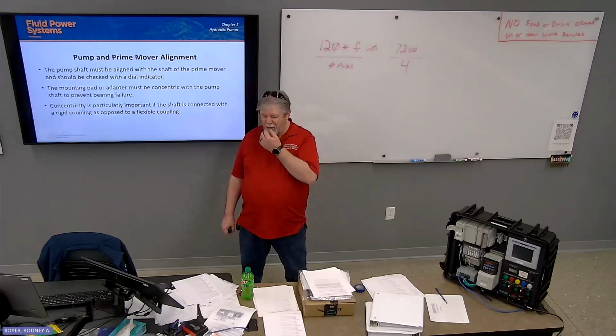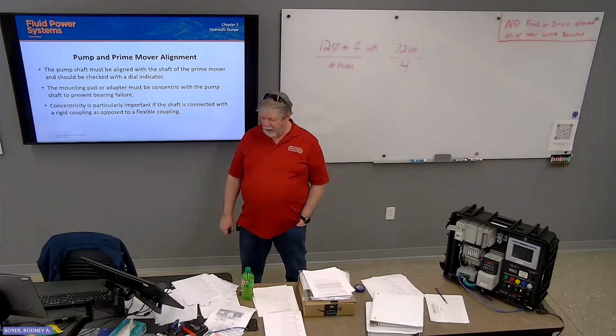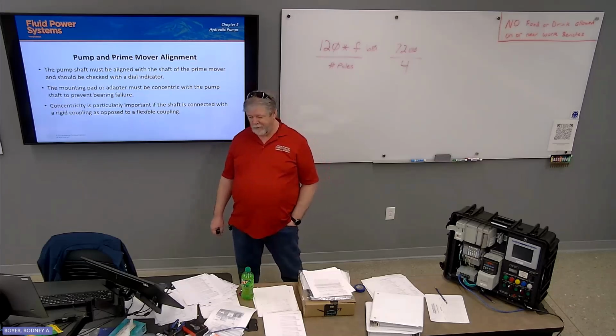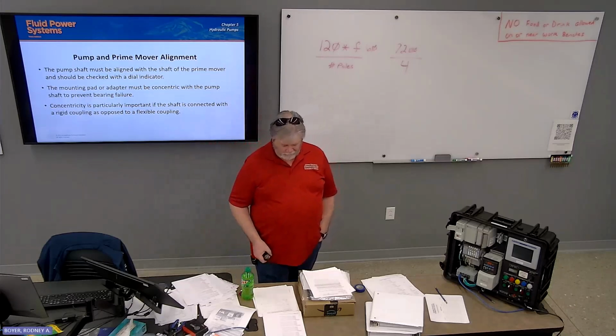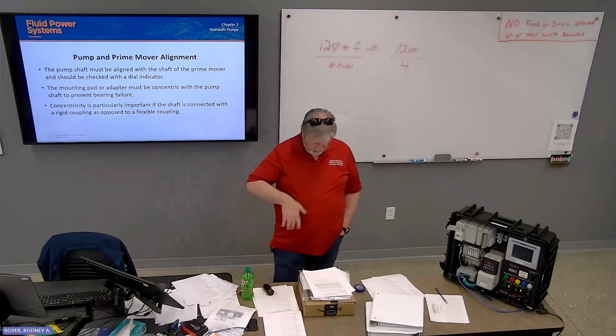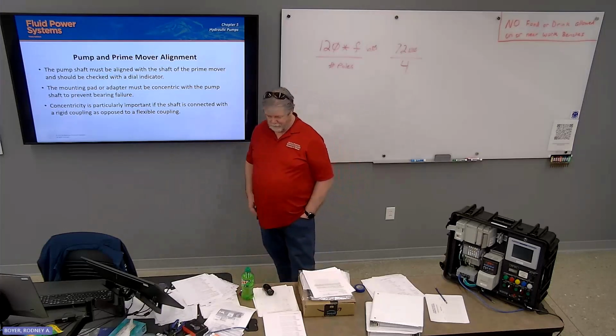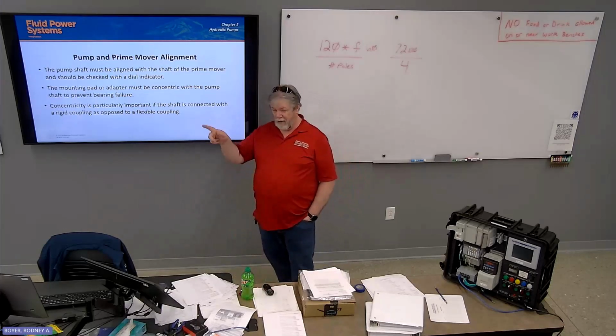Pump prime mover alignment. Pump shaft must be aligned with the shaft on the prime mover and should be checked with a dial indicator. Or they do have laser alignment tools. We actually have a couple of them out here.